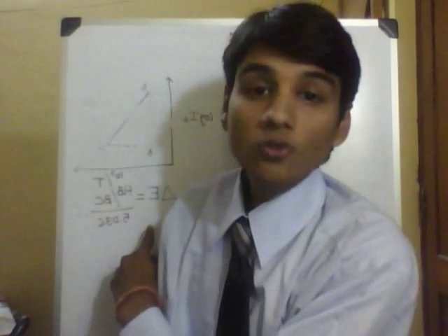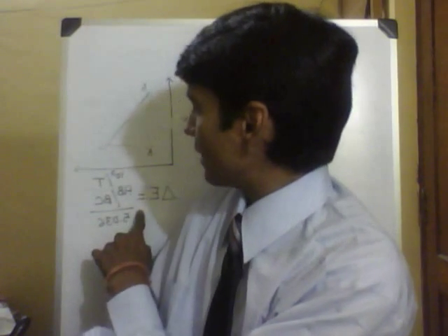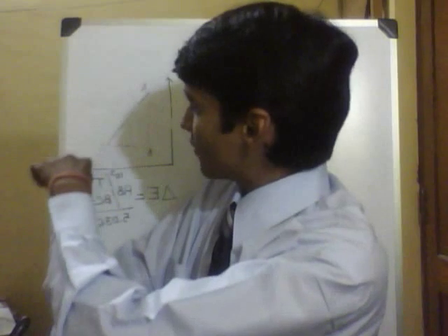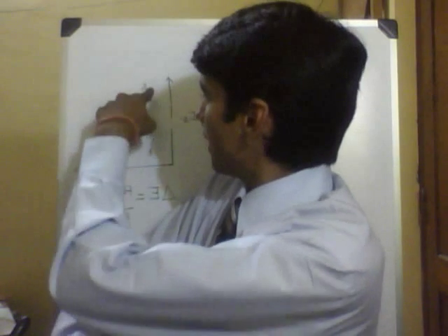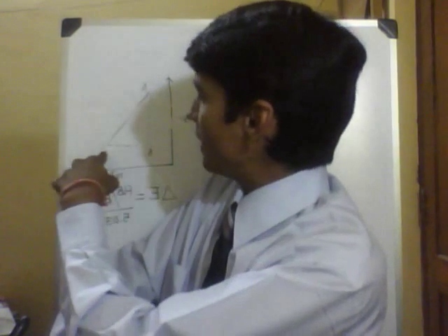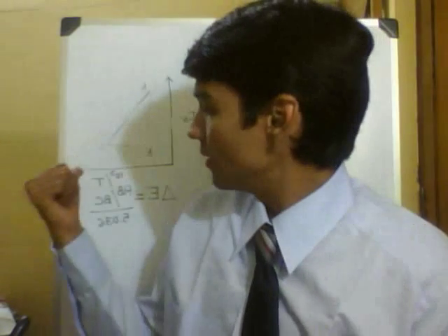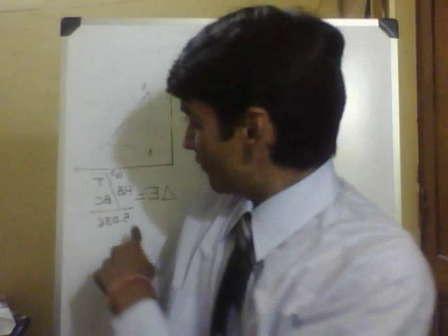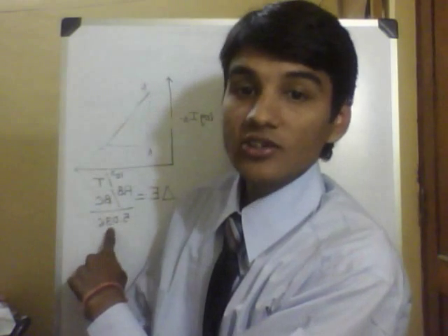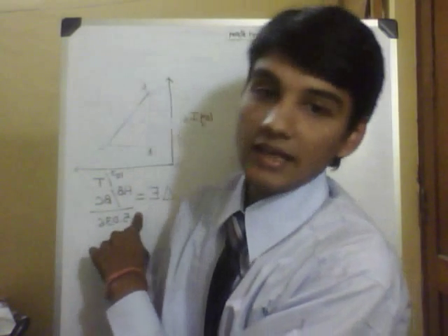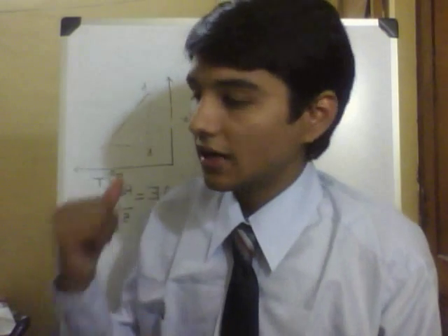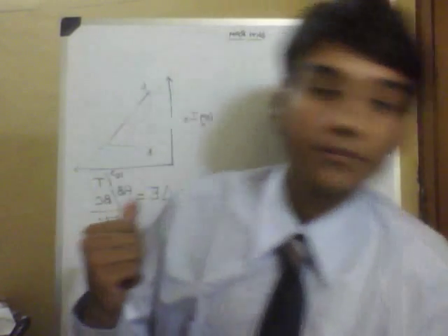To calculate the energy band gap, the slope of this straight line, which is AB by BC, or tan theta of that line, divided by 5.063 will give you delta E, which is our requirement for the calculation.